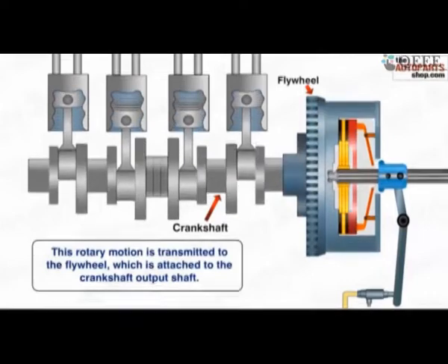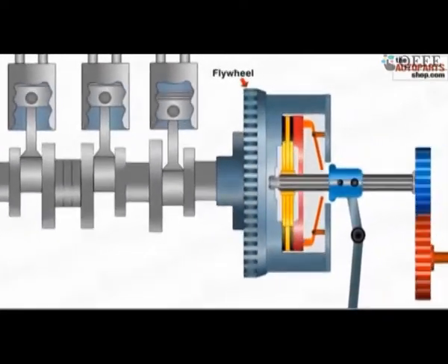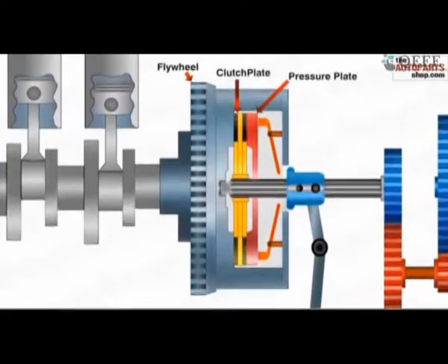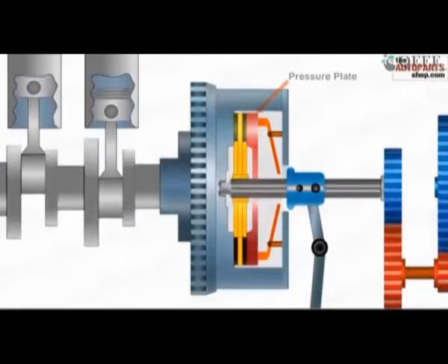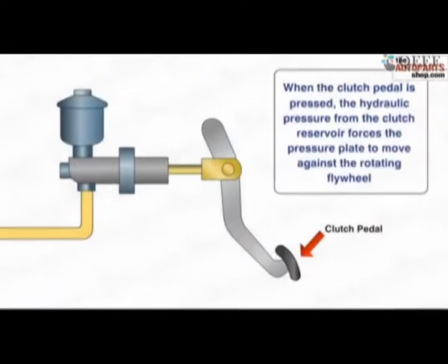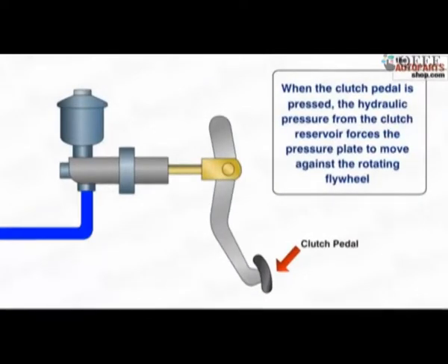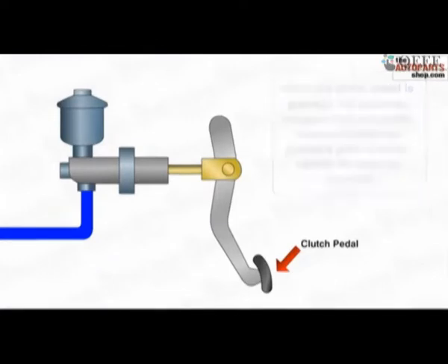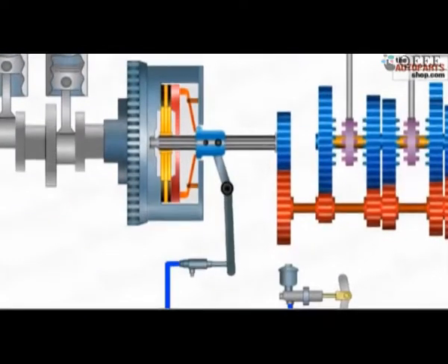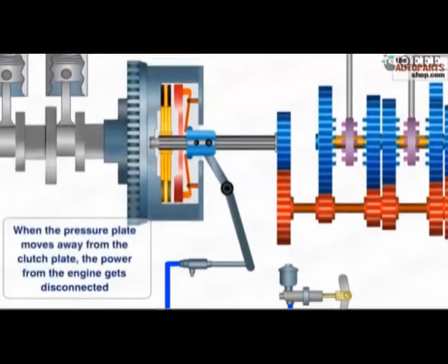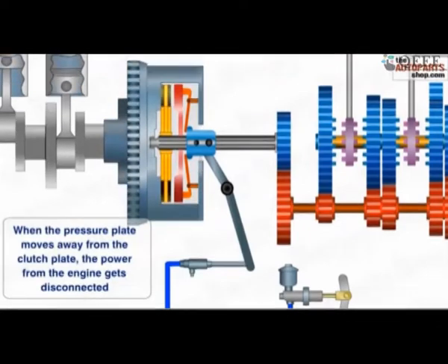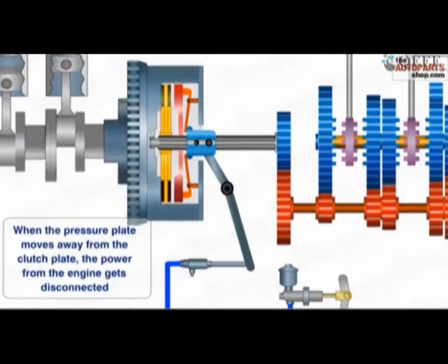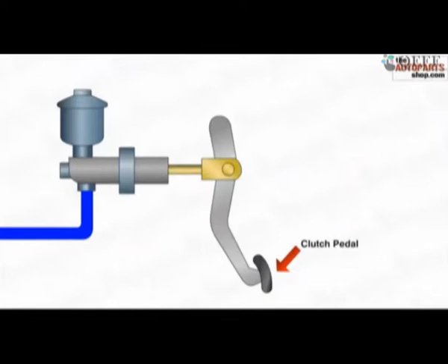And from the flywheel, he will show the clutch plate also. So this is the clutch plate. The clutch is like a mechanical switch. When the clutch engages or disengages, the power is transmitted or it is stopped. So this is the operation of a clutch. The clutch can operate using the principles of hydraulics. So the clutch pedal basically is engaging or disengaging with the flywheel. When it is disengaged, as you see in this condition, no power is getting transmitted.